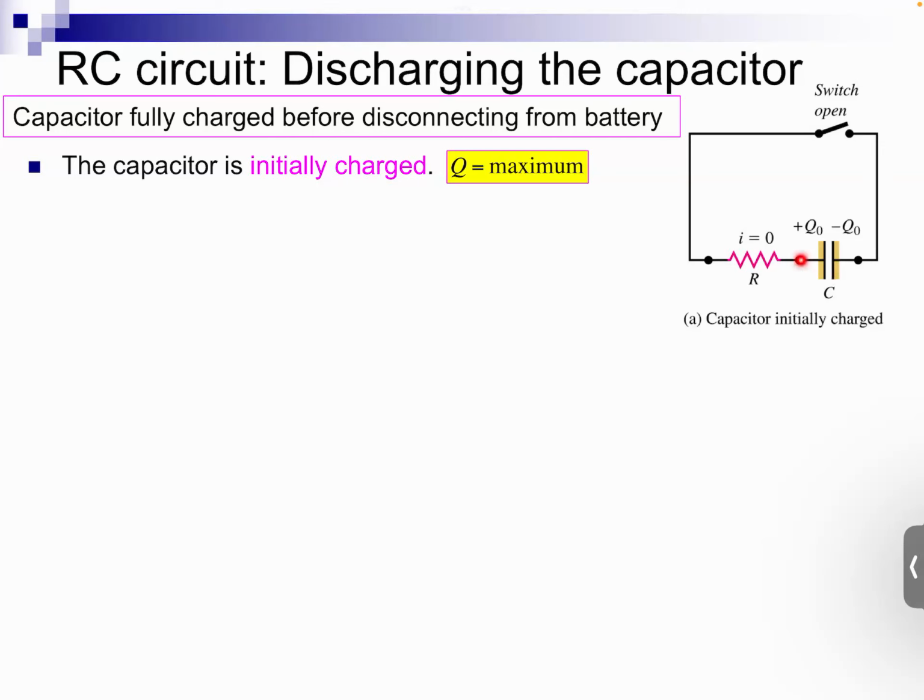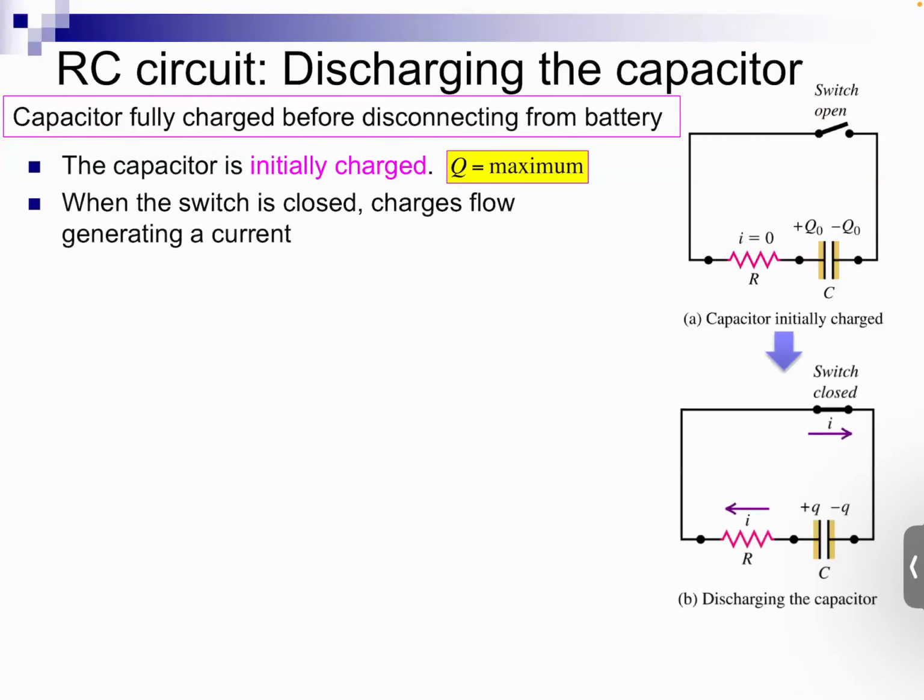And because the capacitor stored energy, it can act like a voltage source, like an energy source. If you look at this capacitor, one plate is positively charged, the other plate is negatively charged. It sort of looks like a battery, looks like a voltage source. So in fact, your fully charged capacitor can act like the voltage source or the battery. So if you connect your capacitor to a resistor or to an external load, or you connect your fully charged capacitor to a circuit that you want to power up, and you complete the circuit, closing that switch, your capacitor then acts like the voltage source, and energy flows in your circuits.